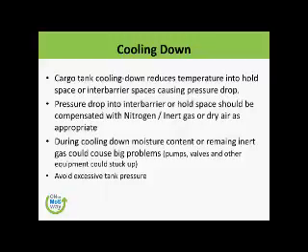So cargo tank cooling down reduces the temperature in all the hold spaces and also in the interbarrier spaces, causing a pressure drop. So if the pressure drops in the hold space or interbarrier space, what is filled in the interbarrier space? Can you tell me? It's nitrogen gas. Nitrogen gas. You have started the nitrogen. Yes. So this is what you are going to watch.